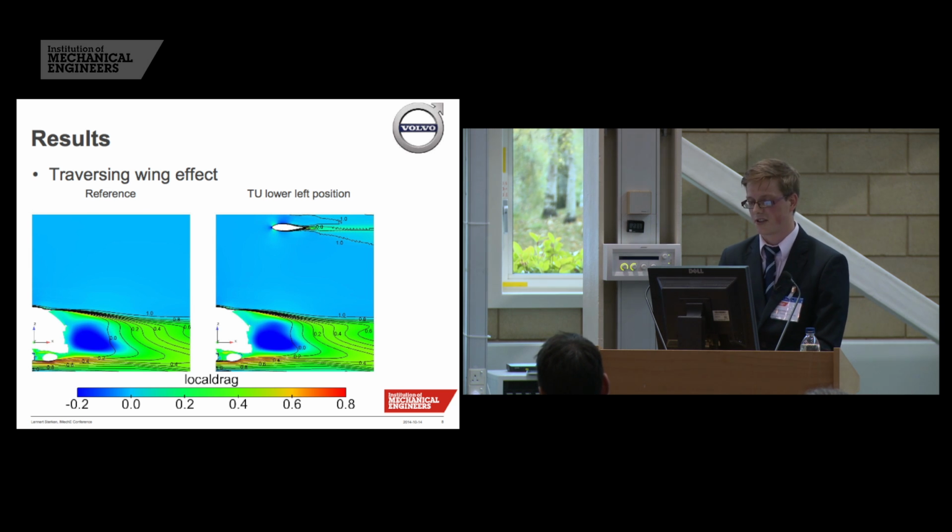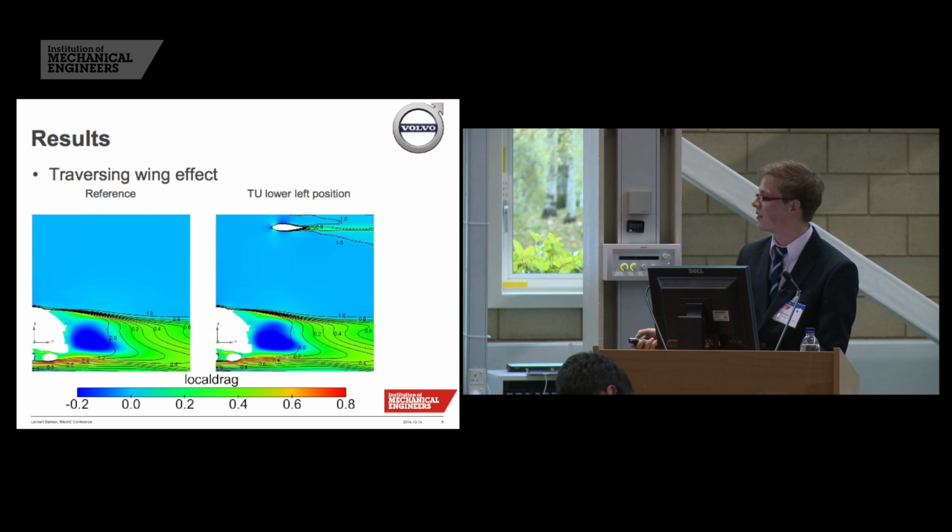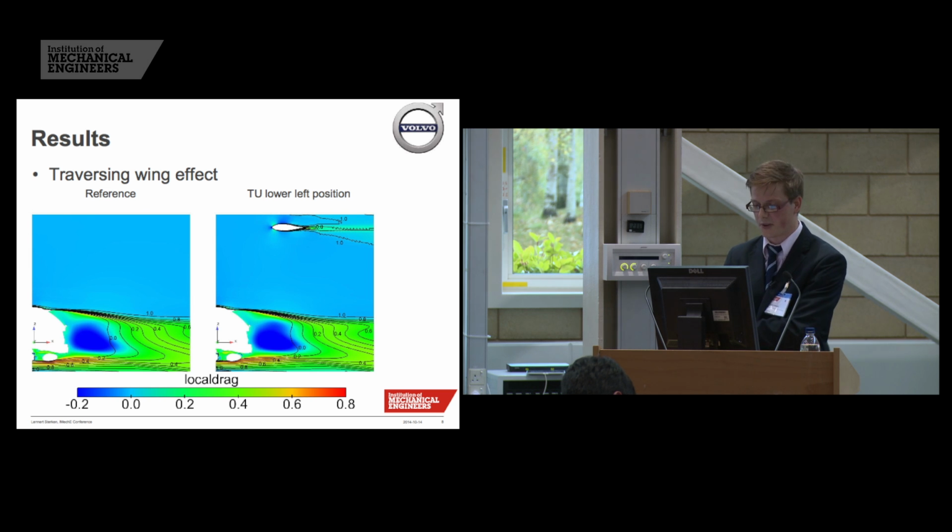We can see that the wing itself generates a small wake, but also that the energy recovery is not as fast further downstream coming from the roof. And from the ground, you see a higher energy region much closer to the ground, which stays longer downstream. So you also get a small lift of the wake.